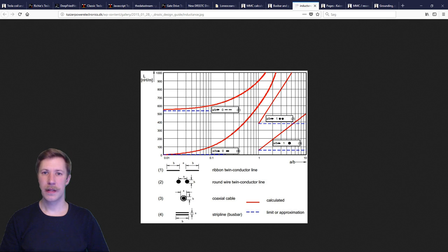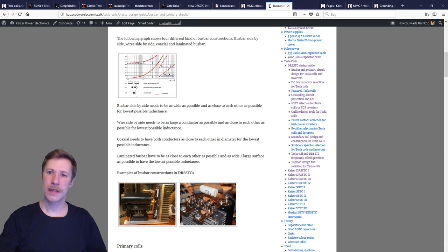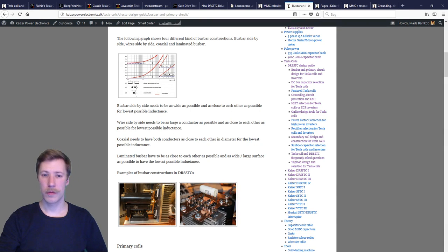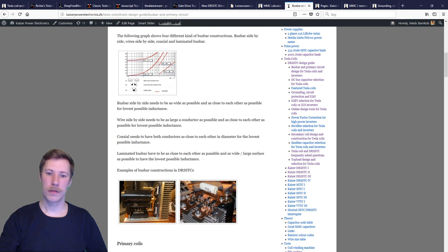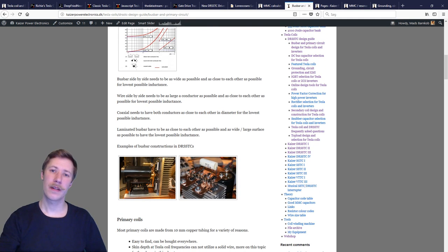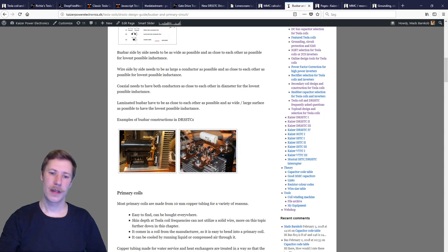The absolute best is the lowest, number 4, which is the laminated parallel plates, because this will nullify the inductance when it's very close together. So that is the most recommended. It's also one of the hardest to do, as it's much easier to just do point-to-point bus bar connections, as I have done myself. But if you do that, then at least use large copper bars so you can ensure as low resistance as possible.